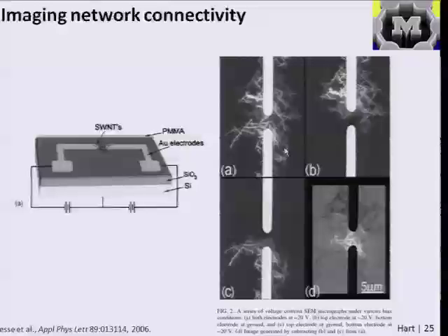And it's also possible, for example, to visualize this kind of transport by electron microscopy. And this is a picture of a technique where they built a little device consisting of a small number or a little tangle network of single-wall nanotubes between two electrodes. And because in the SEM you can view the surface, you can essentially see color or contrast related to charge on structures by charging these electrodes at different potentials, like negative 20 volts or positive 20 volts relative to ground.